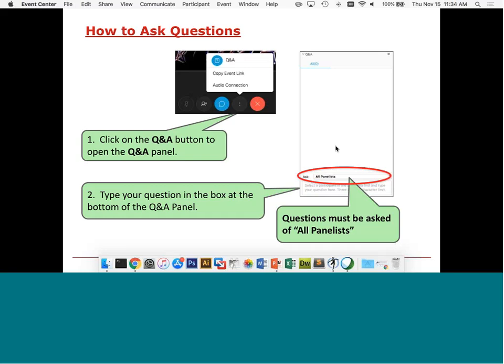So if, for example, in your XML file you just changed all the tags, you would get some of the default parameter values for the muscle model that you switched to that you didn't specify in the old model, and then parameters in the old model that aren't defined in the new are just ignored. So it's not a perfect mapping between muscle models, but you can do that as a first pass, and then change the properties in the GUI.